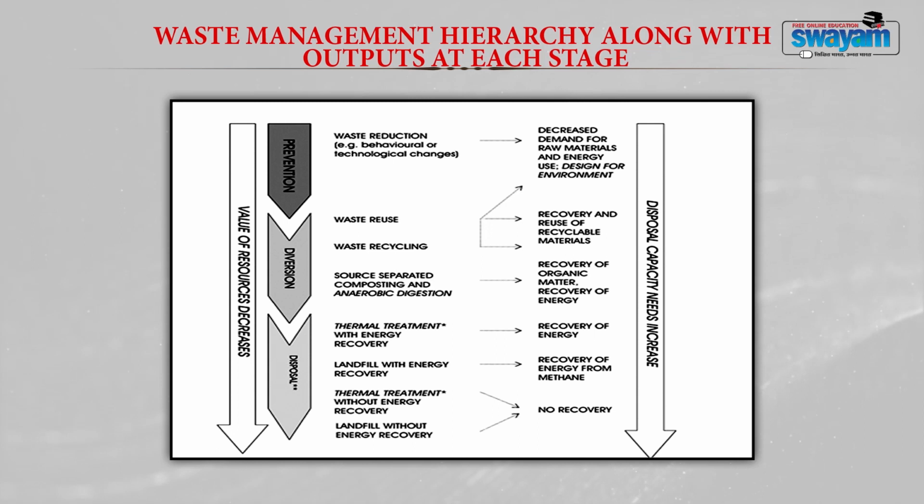Another approach may be landfill with energy recovery, which means disposing waste in the landfill in such a way that energy is recovered, in the form of methane gas. Then there will be thermal treatment without energy recovery, and then landfilling of the waste without energy recovery. So, from this figure we have learned that there are several approaches by which something can be recovered from the waste, and finally, when nothing can be recovered from the waste, only then is the waste disposed in the landfill site.